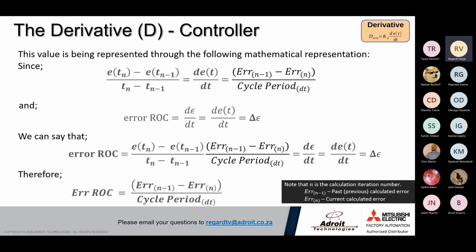An unstable control system will overwork the actuators: your heaters will cool down and heat up very fast but continuously, your control valves will continuously open and close, or your VFD will constantly ramp up, ramp down, ramp up, ramp down, which means the motor accelerates and decelerates. This affects the currents in the coils and reduces the lifetime of your hardware due to currents and the heat that's induced.